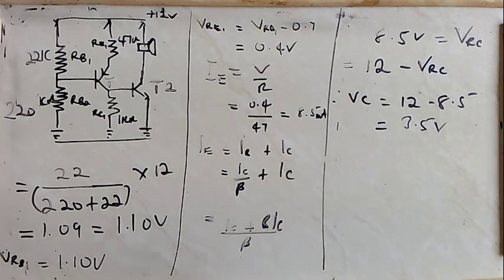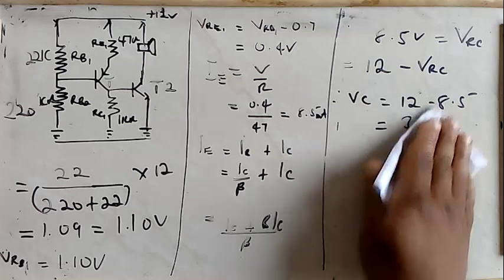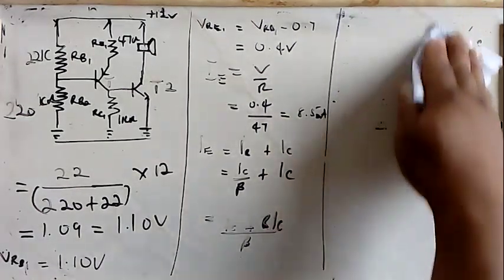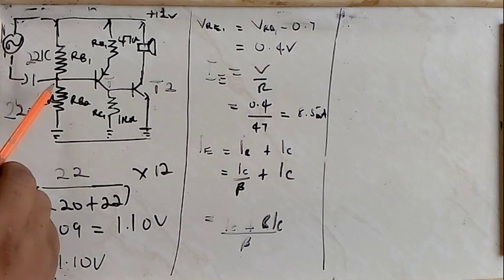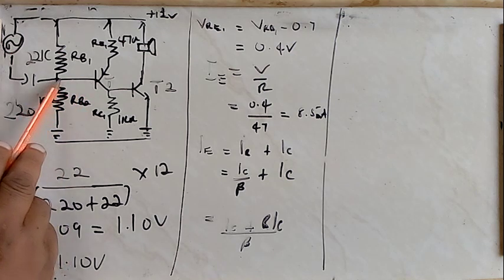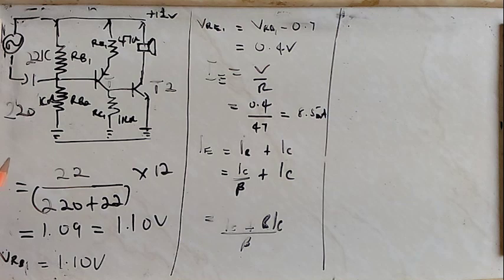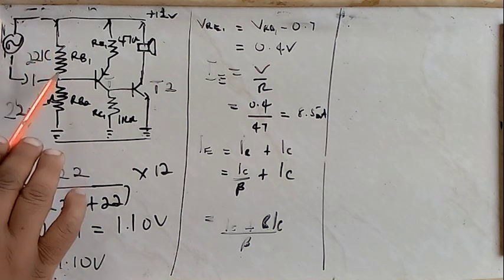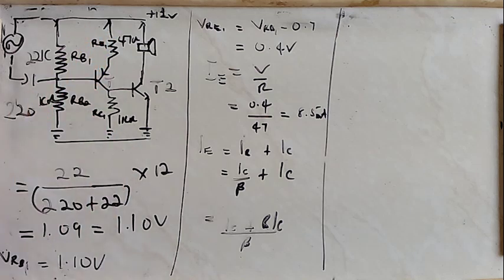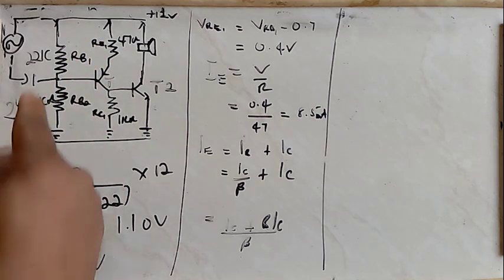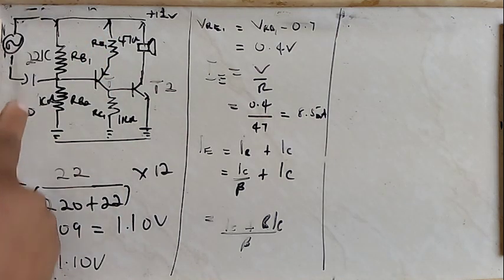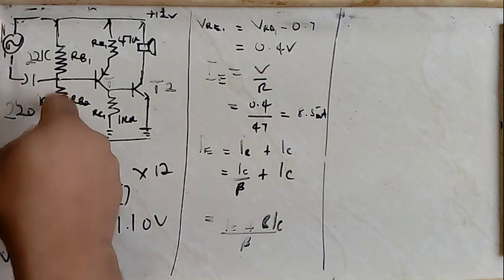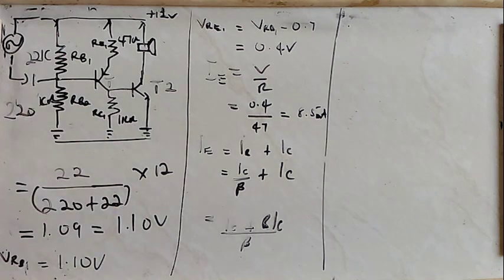Okay, so let's carry on and determine the input impedance of our amplifier circuit. For this circuit, you notice that as soon as you attach the base current, now the current begins to divide. Some of the current will go here, some of the current will also go here. What it means is that even though the voltage divider was in series, as soon as we attach it to the base, the resistors appear in parallel because of the current division that appears.